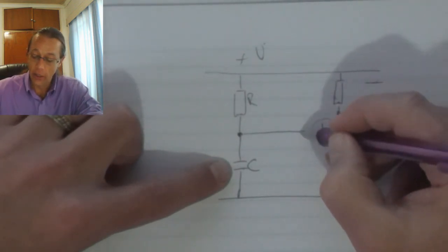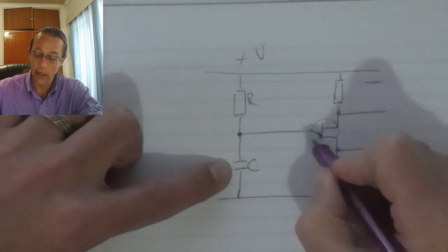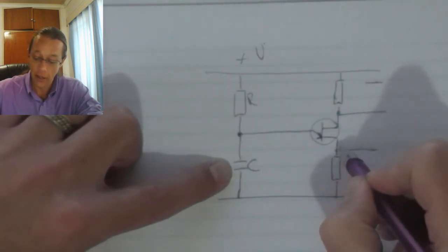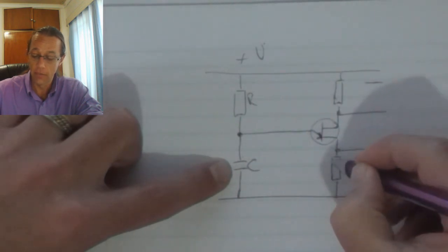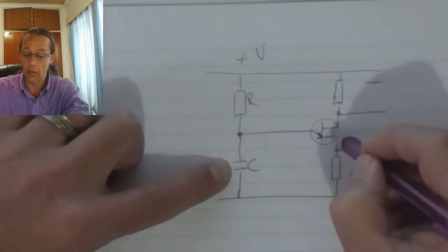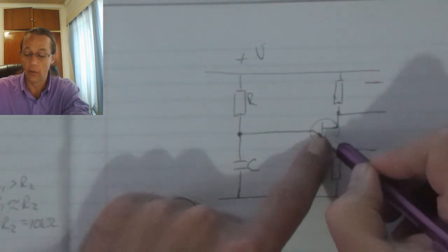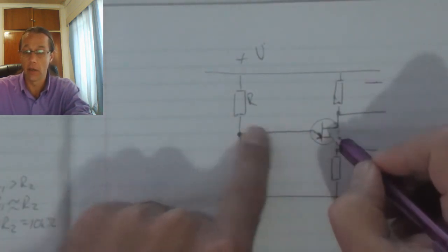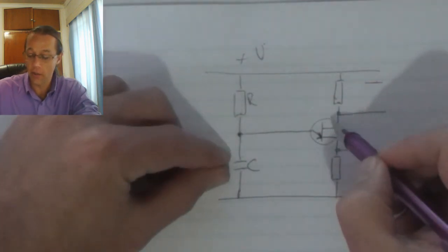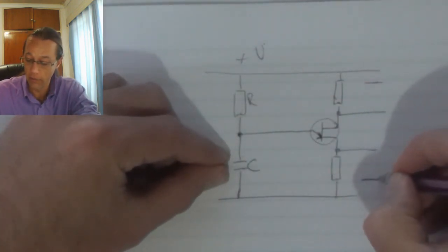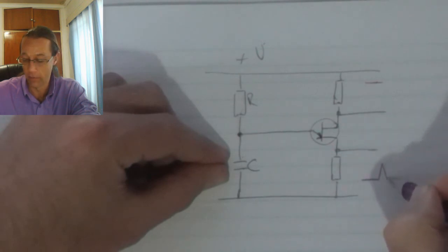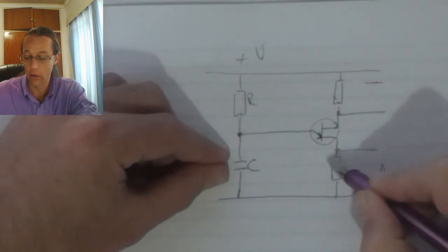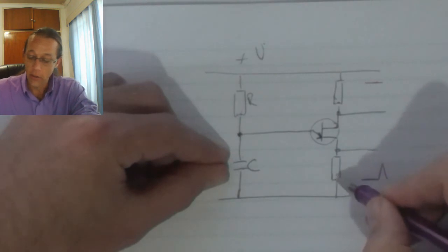When it becomes forward biased, we now have a parallel conduction flow taking place. That allows this capacitor to discharge through this resistor, and the current will then separate through that resistor as well as that resistor. So while the capacitor is discharging, I will get a brief spike in the amount of current, and as a result I will get an increase in the amount of voltage generated on this resistor.